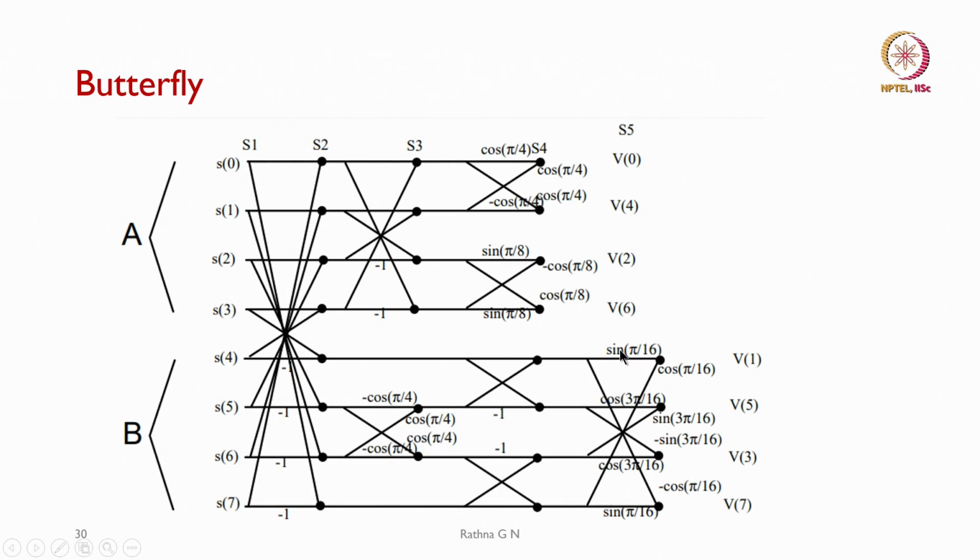Later on we went on to use butterfly structure to show that the order of multiplication for the 8 by 8 bit 1D DCT needs 64 multiplications and 63 additions, which can be reduced using the butterfly structures to 13 multiplications and then 27 additions. So, that is one of the techniques we used to show this. So, you will be seeing cos and sine functions being used here.